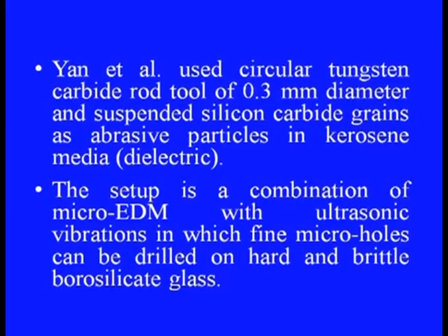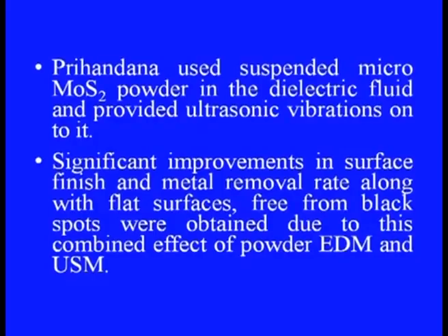Yan and his co-researchers used a circular tungsten carbide rod of 0.3 millimeter diameter and suspended silicon carbide grains as abrasive particles in kerosene, which works as the dielectric, in another attempt at hybridization of this process. The setup is a combination of micro EDM with ultrasonic vibrations, in which fine micro holes could be drilled on hard and brittle borosilicate glass.